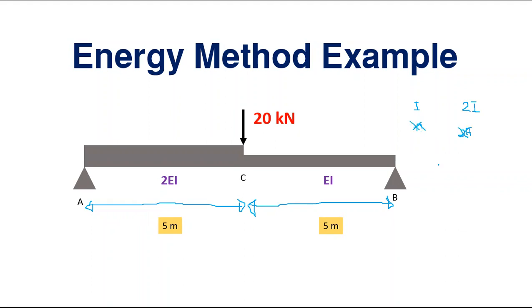So one thing possible is, if it is a rectangular section, the I value is BD cube over 12. So you can see if the depth becomes twice, the D cube will be 8D cube. So if others remain the same, the I value becomes 8 times I. If this is I, this is 8I. So this cannot happen. So how should this value be 2D cube at the end if it needs to become 2I?